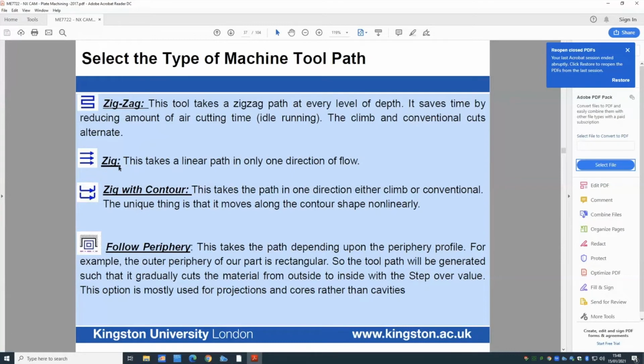A zig takes longer for you to do, but one of the cons of that is, a good example Dina used in her session, is when you're cutting the grass for a soccer match or football match. You can see some kind of line which comes from it because it's one cut direction. But the benefit is, if you do it precisely, you might have a better looking result at the end because you're not removing the material double.